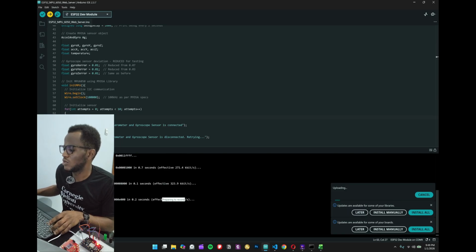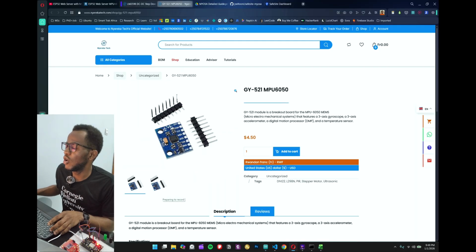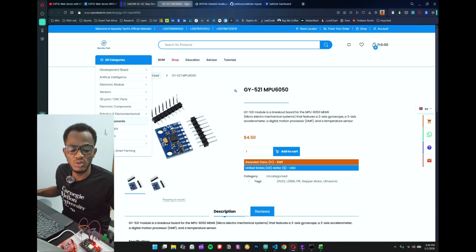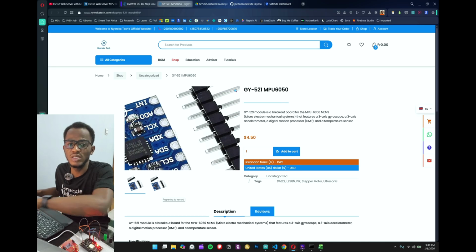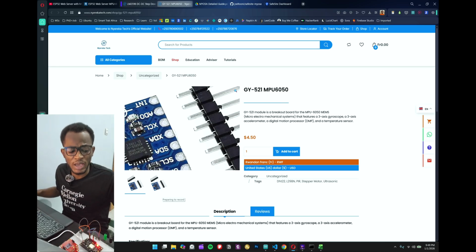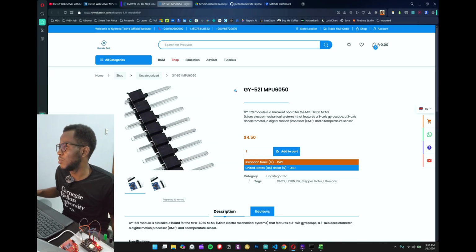While this is still uploading, in the documentation we also raised an issue about power, because we intend to power the whole system not with a power bank, making it compact. We're also going to 3D print a case for it, and this produces 7.4 volts. So we have to get a step down DC to DC converter. The one we have here is a step up, so we could not use this. When we are able to bring that to 5 volts, we'll be able to power our air quality sensor. This is an MQ135, so we also intend to integrate it into the system.